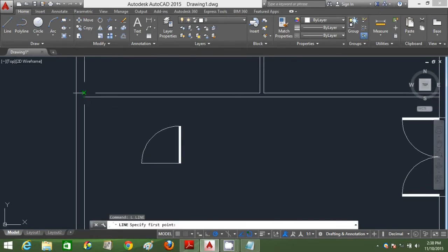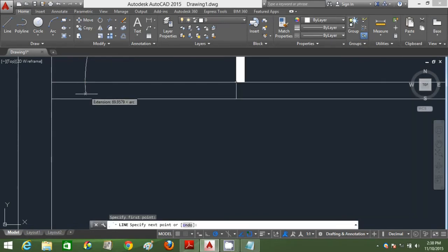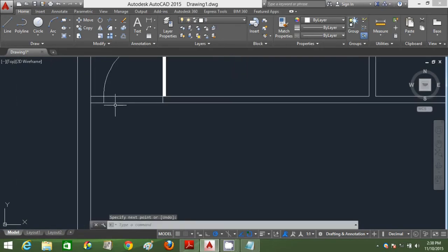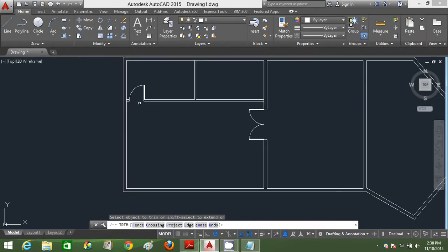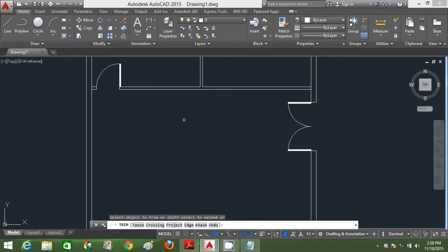Okay, and I'm just drawing a reference line here by 200 mm. So I'm gonna move this. I'm going to move this on that particular reference line. Alright, so I'm just creating the boundary for the door. Okay, so click line, draw that line properly straight, select the overlap line, delete it, trim out these portions. Alright, so I have to delete the overlap line first before trimming it out.